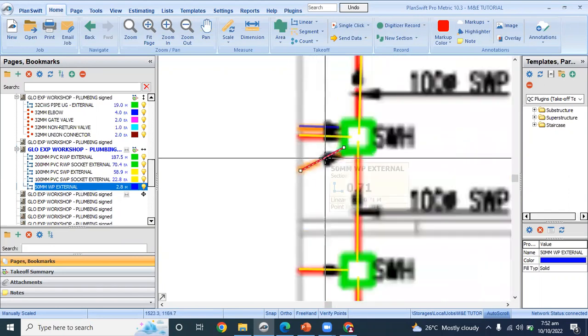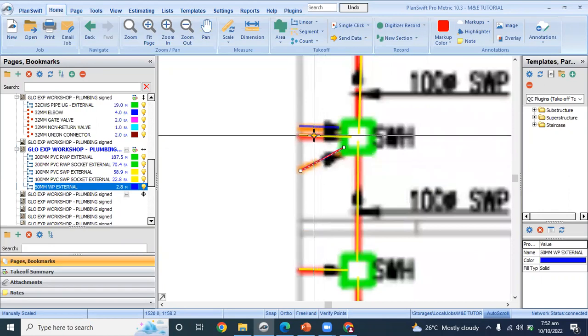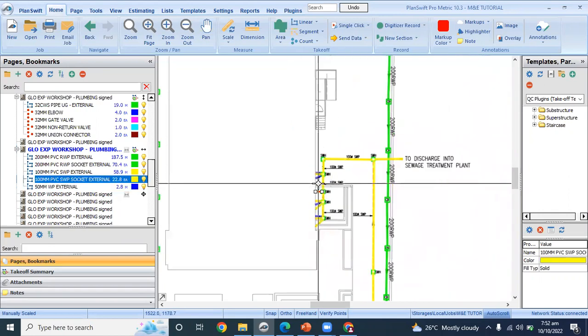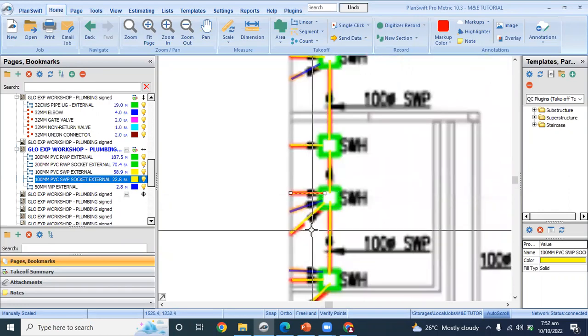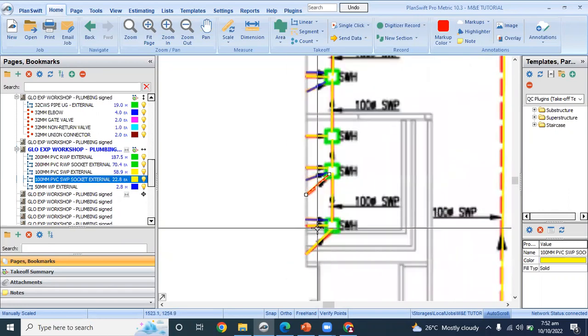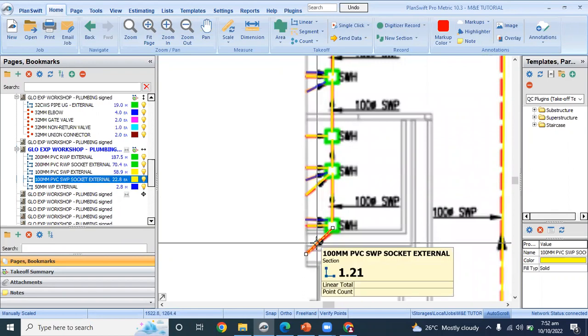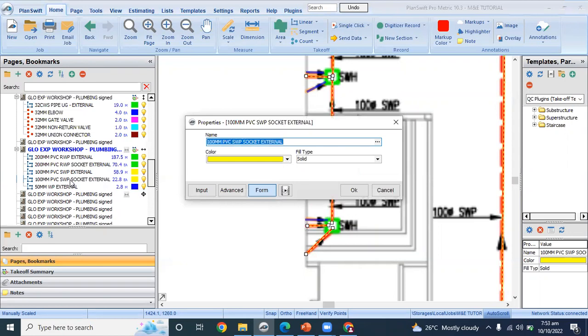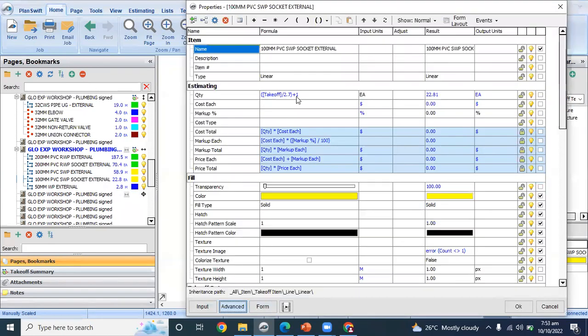So how many short pipes, 100 mm short pipes, do we have? We have one here. We have two. We have three. We have four. We have five. We have six. So I'll be adding 6 by, let us assume the height in which the rise is 200 mm, so I'll be adding 6 by 0.2 to these quantities of 100 mm pipe.